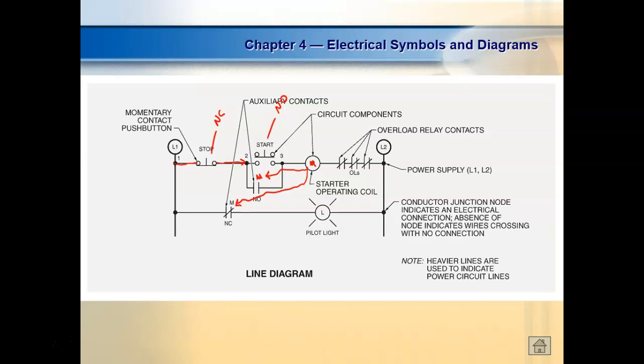Now I come over here and press this button. I don't have to hold it down, because as soon as I press that button, all of a sudden this contact closes. This guy right here closes. This guy right here opens, right? The light should go off. Then I let go of the start button. Then we pick up this secondary path that keeps current going to the relay coil. So it locks itself in, right? Understand that. This is called a three-wire circuit.